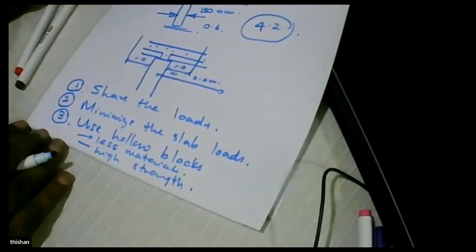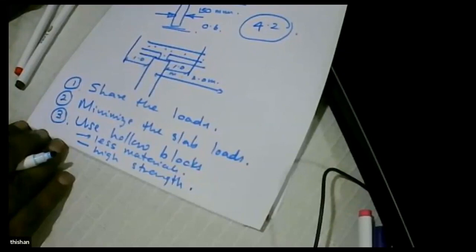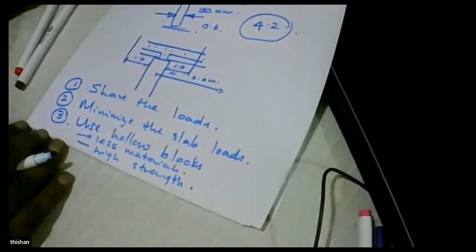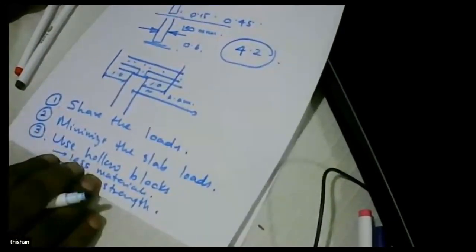though the wall thickness is only 150, and you can support this lightweight system up to 4 floors. So any apartment building having up to 4 floors, this method may be feasible, because our idea is to minimize the amount of concrete in the slabs, minimize the amount of material in the structure.